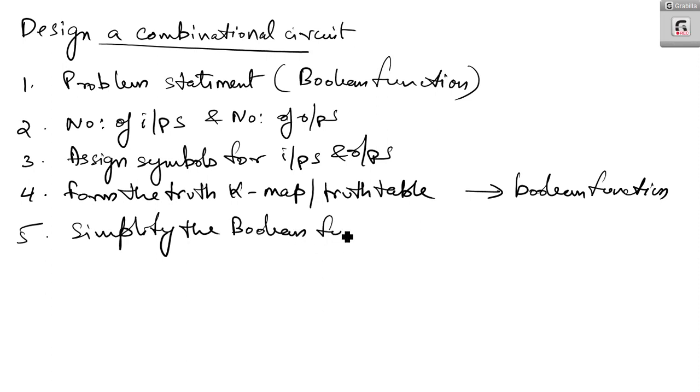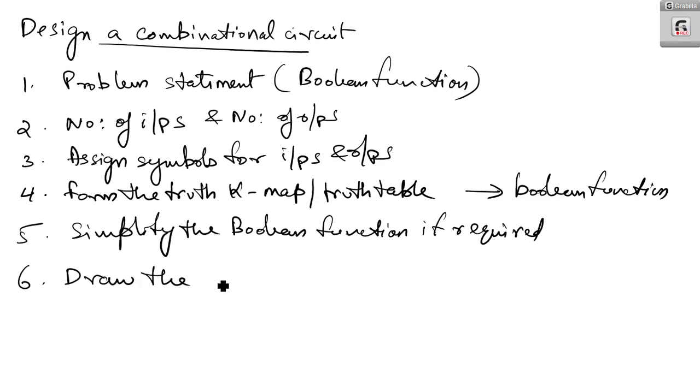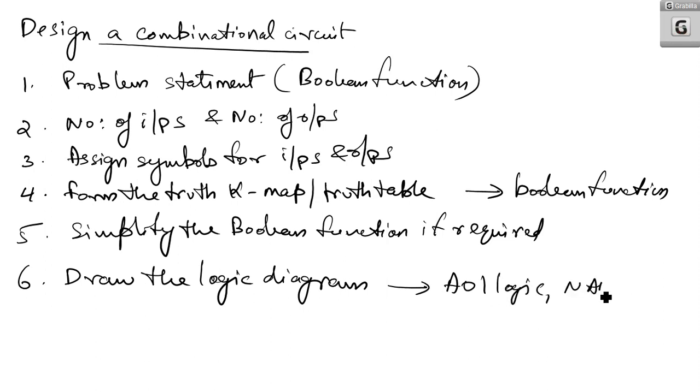And the last step is to draw the logic diagram. You can use AND or invert logic, NAND logic, or NOR logic. So you can go with any of these three methods.